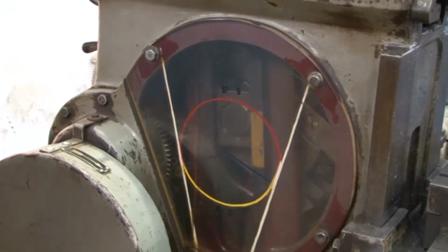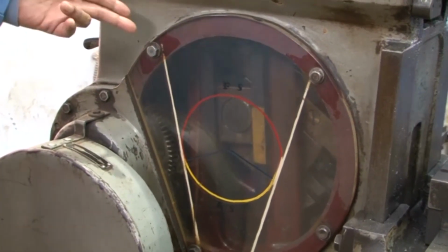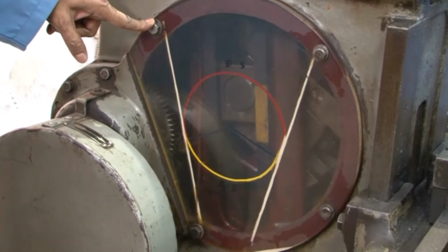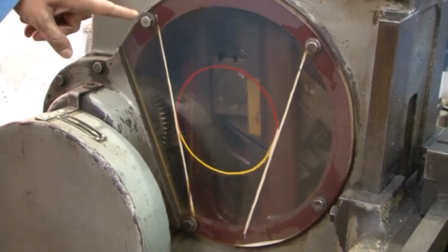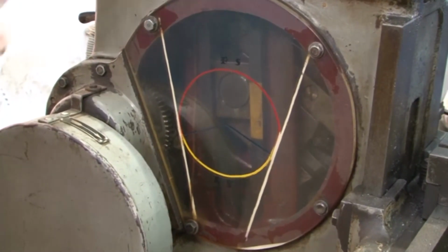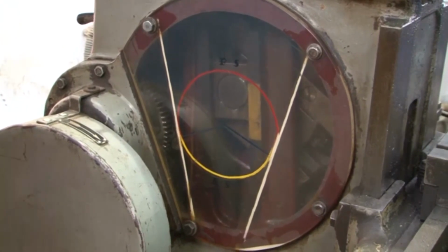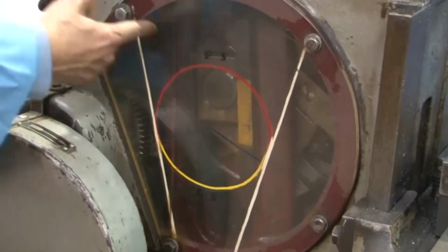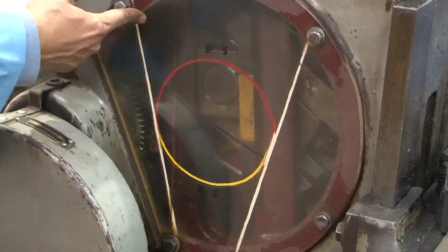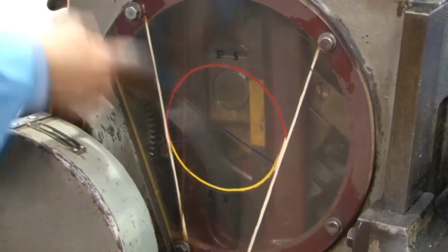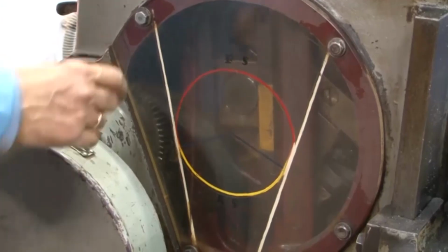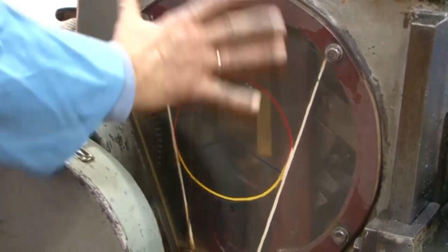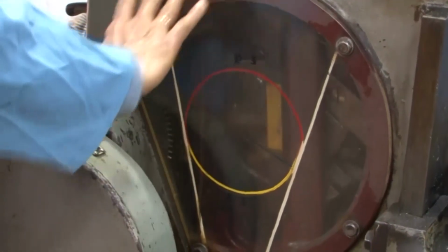Well, here you can see there is a purposely made window for demonstrating it to the students. So, here through the window you can see the quick return mechanism, which, as I mentioned, is called the Whitworth quick return mechanism, and here, as you can see, there is a bull gear, all right, and there is an arm which actually reciprocates the element which is there, as you can see, and during that reciprocation it actually goes like this, to and fro.